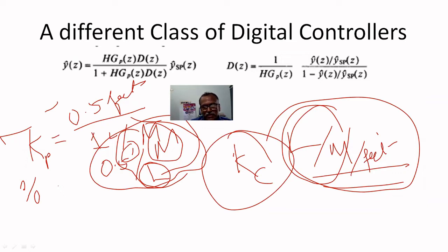But after that, you should work on percentage. Why I'm telling this is you should see the controller gain, controller output, process output, error, everything you should see in percentage. Then only you can tune any process. That's why we should see everything in percentage.